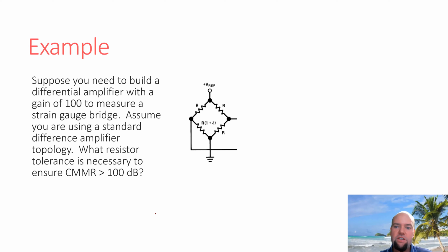A lot of strain gauges do this, where when the material gets stretched, its resistance changes. There are a lot of chemical sensors that work this way. Basically, this chemical sensor is a resistive material that absorbs a certain molecule at a certain temperature, and when it absorbs the molecule, the material inflates, dissolves the molecule inside of it, and causes it to grow.